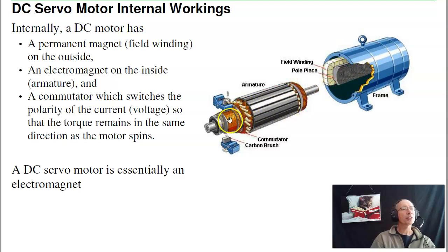These armature brushes rectify the signal. So I've got a sine wave. If I just take off the peak of a sine wave, I get a torque. Then as it rotates, I pick off the next peak, and it gets a large torque going to the magnet. As it starts to rotate, I then shut that one off, grab the next peak. This gives you an almost constant torque for constant current.